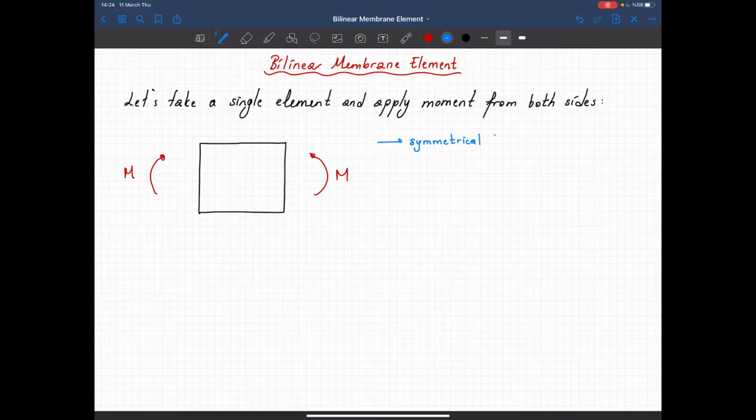With the symmetrical bending mode, there is no shear stiffness, or we can just say that in this case shear strain should be zero. Or, from the force side, we have constant moment on this element, shear force is equal to 0, hence there shouldn't be any shear deformation.